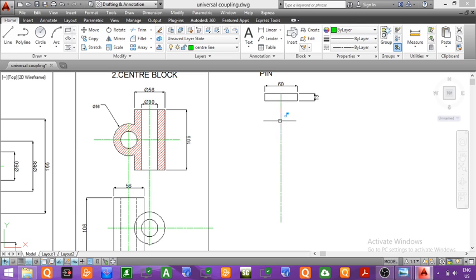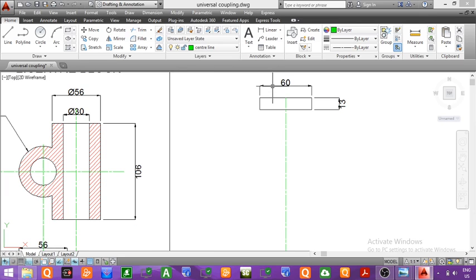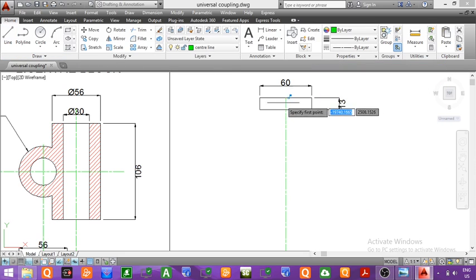Now the diameter of the lower part, you can see from the figure, the diameter of this lower cylindrical part is equal to 30 mm. So this lower cylindrical part, which is of length 186 mm, will have diameter as 30 mm. So now we will mark the diameter, that is equal to 30 mm. For that we will take a distance of 15 mm towards right. So from this point you have to take a distance of 15 mm towards right and 15 mm towards left. Then we will mark the length is equal to 186.